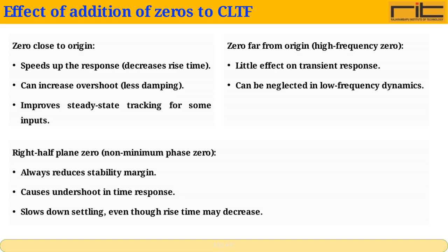On the plus side, such zeros can improve steady-state tracking for certain types of inputs, helping the system follow the desired signal more accurately. Next, a zero that's far from the origin, often called a high-frequency zero, has minimal impact on the transient response. It mainly affects the system at higher frequencies and can usually be ignored when analyzing low-frequency dynamics, which are often more relevant for control performance.